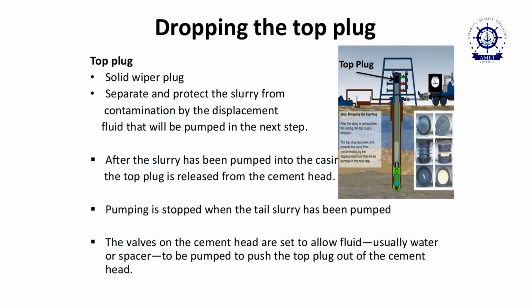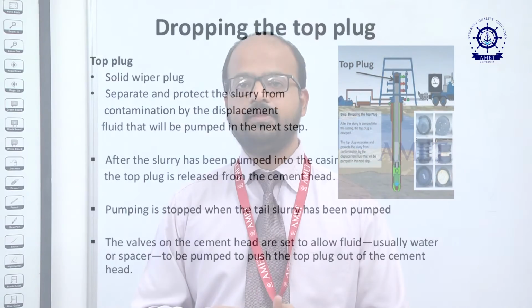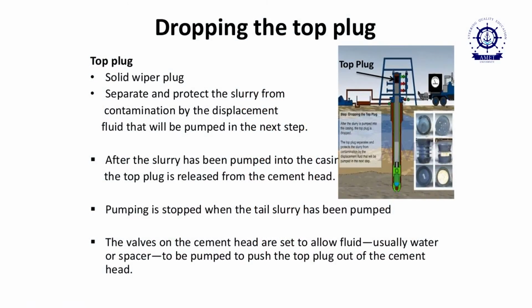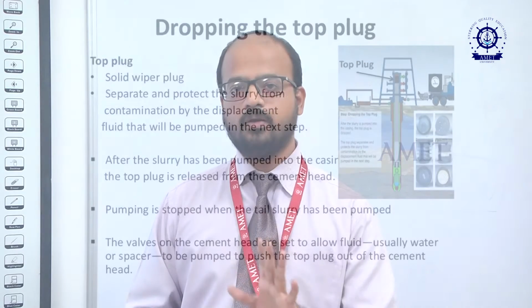So again, if you come to the displacing fluid, if you use it directly along with this tail slurry, then it starts to mix together, it starts to contaminate, as well as spoil your cementing process. Now what I have to do is prevent these two from mixing. So again I have to separate them. For that purpose, I am going to use another plug. That plug is called the top plug.